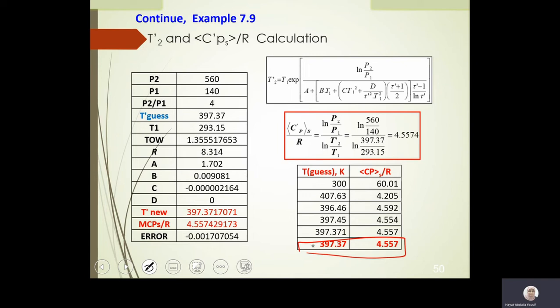And if I got the liquid property as inlet and outlet, then how can I get W? This delta HS is simply H2S minus H1. If H2S and H1 are the same, especially since the temperature difference is mostly negligible with the pump, then this term is zero, and that's why it's not appropriate to consider this assumption here in the work. In other words, subcooled properties are not available in thermodynamic tables, and that's why we do this approximation. For that reason, the way we are going to find the isentropic work here is using this relationship.